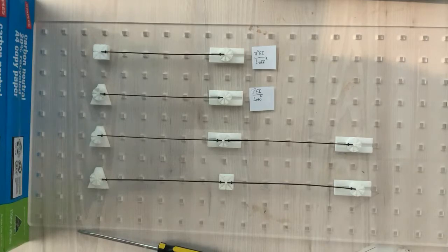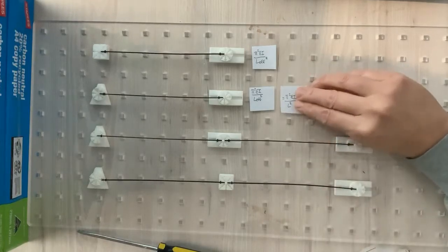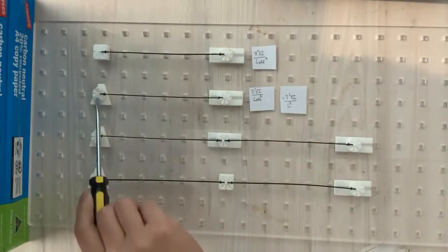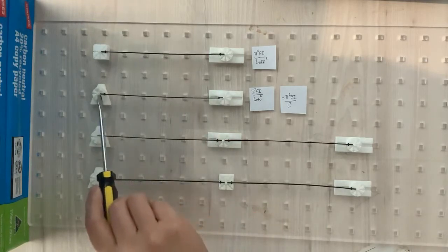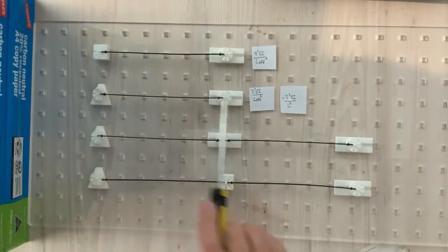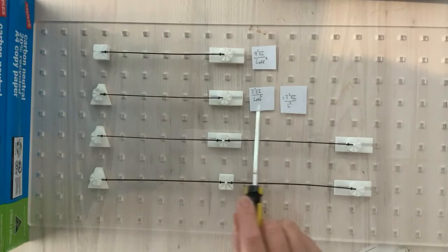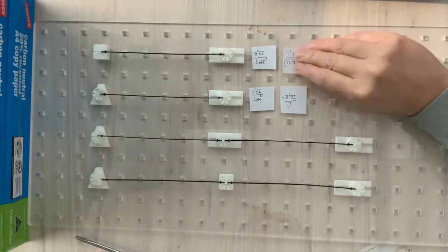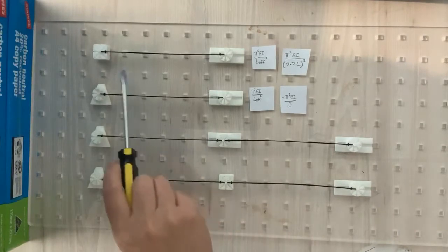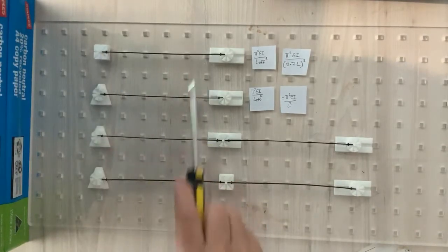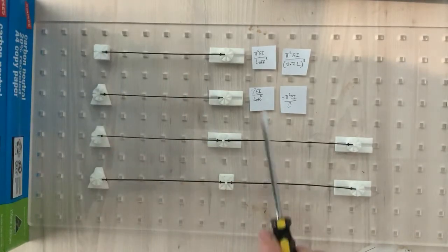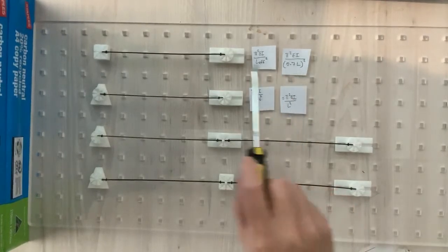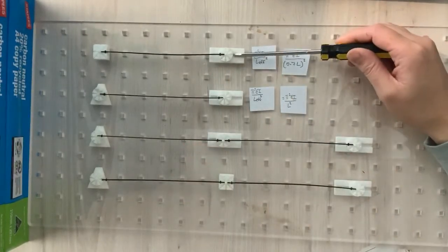So in this case here, that pi squared EI over L squared would be the same as the effective length, or we could say the effective length factor is 1 because L effective and L are the same. But in this case here, because of the change of boundary condition, another way to look at it is to say that the effective length has reduced.